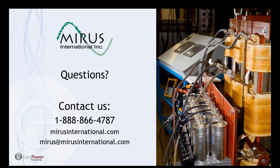That delay in the firing introduces a displacement power factor. The current ends up lagging the voltage. So you end up with a drop in displacement power factor. It's always lagging. It's always going to be a reduction in displacement power factor that's lagging. So if you have capacitors in the system, in that scenario, additional capacitance will help somewhat to offset that lagging displacement power factor that's introduced by the thyristor bridge.